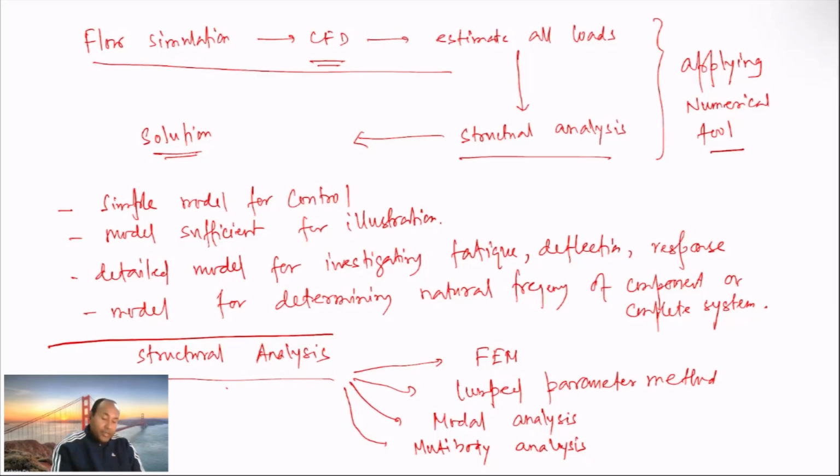Obviously, either you can have a simple linearized model to carry out the analysis, or you can have a slightly more complicated lumped parameter method where you couple together different components and consider them as one big unit having some inertias and stiffness, and you can solve that.